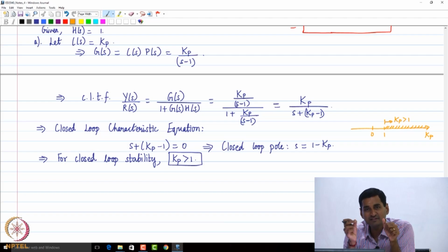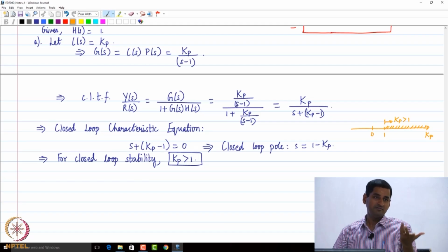Then I go to the experimental system and tune, and I have to fine tune my gains. That step is a final step which we always need to do, because we remember that all the analysis that we are doing is approximate. We are approximating the practical system as a linear time invariant system and then doing all this analysis, so we have to give some tolerance to those approximations. Okay.